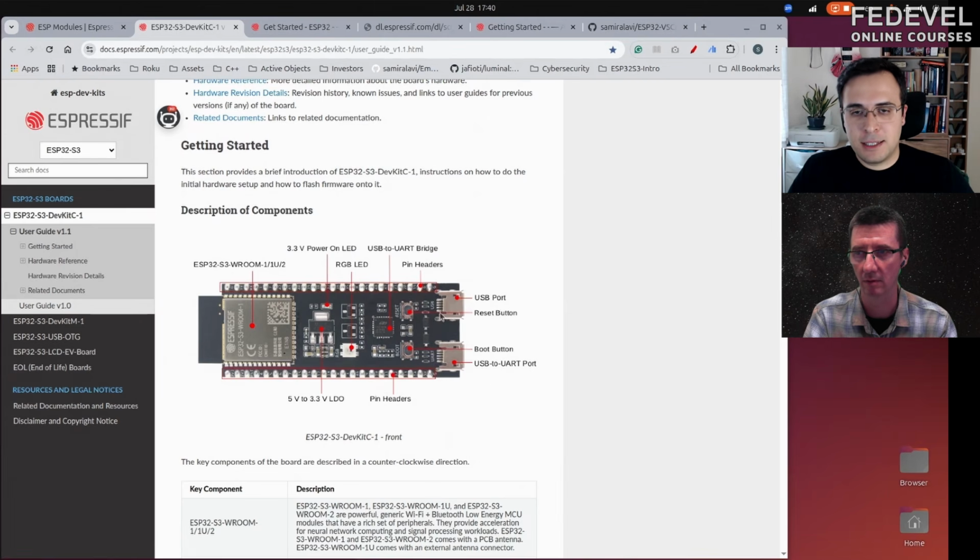Exactly, yes. This is the second application of this USB port. This USB port is exactly connected to the USB pins of the Espressif chip, and it gives you the JTAG profile on the USB. So basically, it is an embedded JTAG debugger on the board, which you can connect directly and then install the driver. They have put documentation on the website on how to connect and install the driver. On Linux, it is already shipped with it.